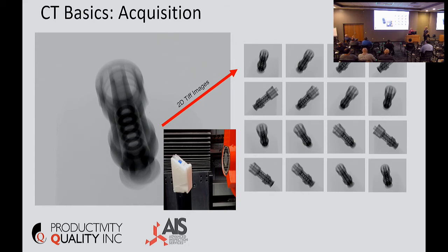And here, again, on this whole density thing, it is just sitting in a foam block that's incredibly not dense, and so that just kind of washes away. So we can put it in some kind of soft material. We've got the stuff that you pot your plants in, or just pink styrofoam or other kinds of foam. We can make a fixture, put the part in the fixture, and the fixture just goes away when we actually do the CT image. Yeah, what Keith is talking about right here: here's the part sitting on foam, but in the actual scanned images, you cannot see the foam.